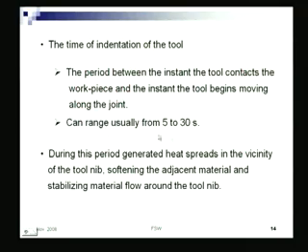That time can range from 5 to 30 seconds, because the longer it is there, the more heat it generates, but after some time it attains a steady state. It does not generate further heat, but the cooling starts, because when it is rotating and has gone inside, the friction has decreased.